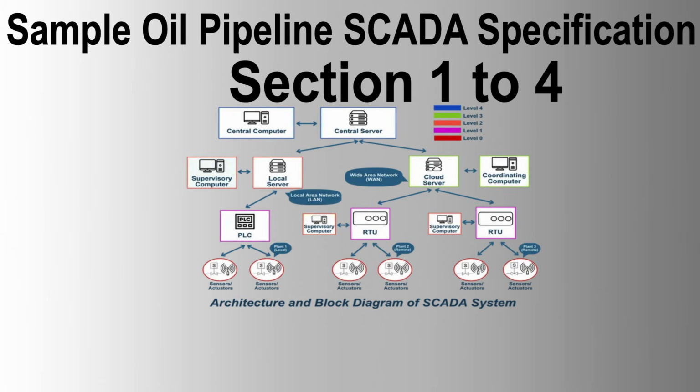4.11 Terminal Tank Farm Management System, TFMS, Interface. The SCADA system shall interface with the Terminal Tank Farm Management System to manage and control tank farm operations. Dual Redundant Serial Interface Links, or Gateway Running TCP/IP, shall be used for communication between LCC and TFMS.